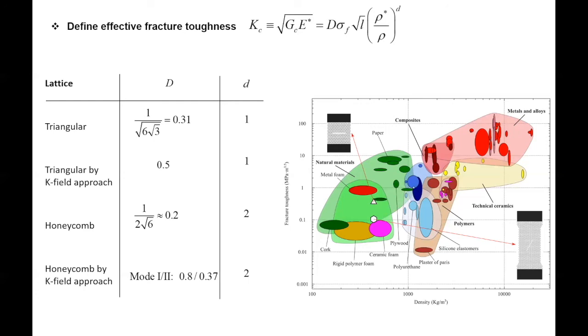Back to your question, Oscar. So there are two families of people, right? When you ask about how do you do fracture in those lattice metamaterials, I think two extremes. One is the minute you fail, remove one strut, you don't have a continuum anymore. Stop doing anything continuum with fracture mechanics. It's not going to work. The other family is like, just have a little bit of a large crack, have a large domain, it should all be fine. It's like linear elastic fracture mechanics. We're a little bit in the middle.